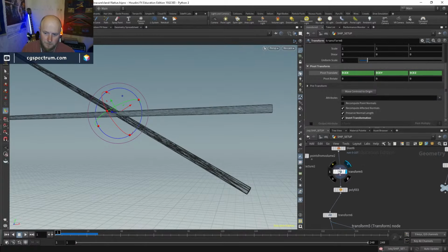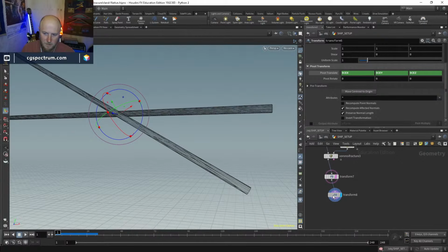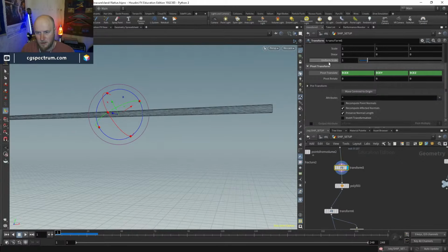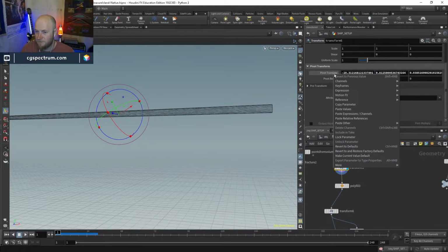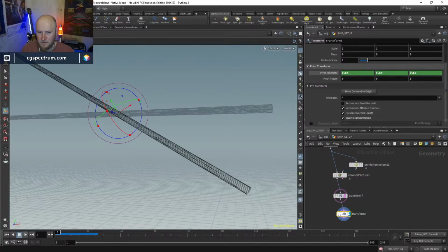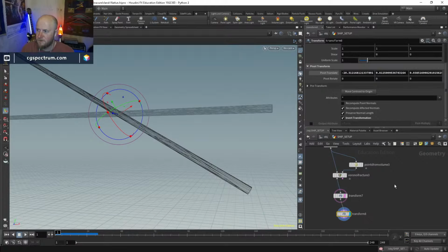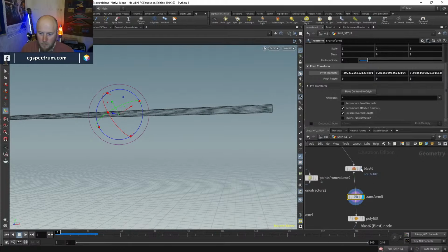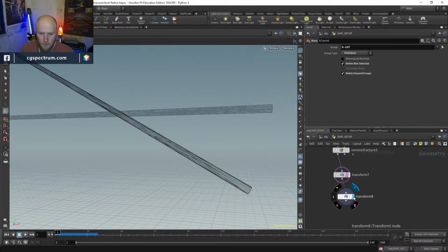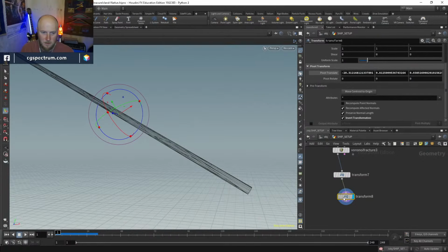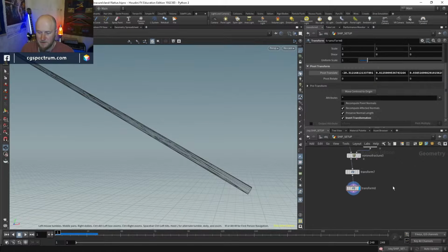What we should do is actually just break this expression. So calculate the centroid, get it, delete it, copy this value, and then don't use $CX down here, but paste that same value in there, and then you saw it shift a little bit. If we then compare the two, they're now identical and not moving. So you always have to be careful when you're dynamically calculating the centroid of something, because it can change, especially if the object has moved slightly or you've done something to it.